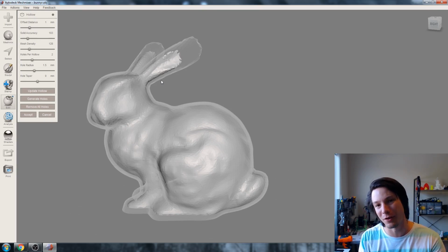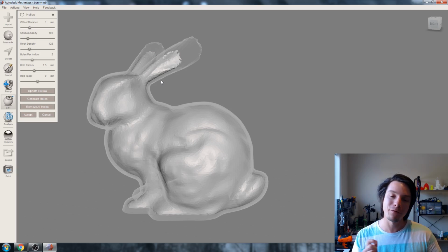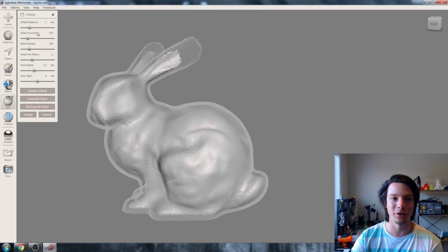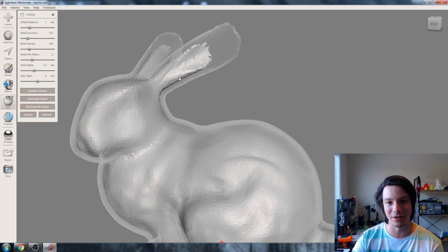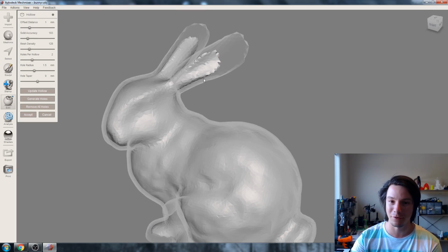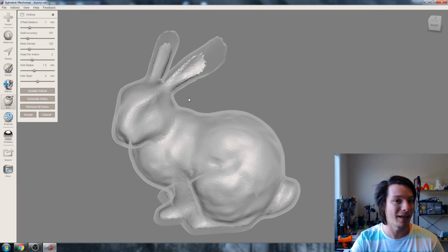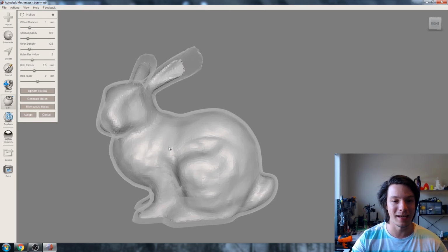It's the inside of the model, so you don't really have to worry about a high triangle count normally. But if you have a very curvy, detailed object, if you go too low on solid accuracy or mesh density, you might start to have clipping, where this inside hollow will start going through the outside of the shape. On default, it's normally fine, but if you do start having issues, for example, it takes too long to compute, you might want to ramp it down, or if you start having clipping issues, you might want to ramp it back up.